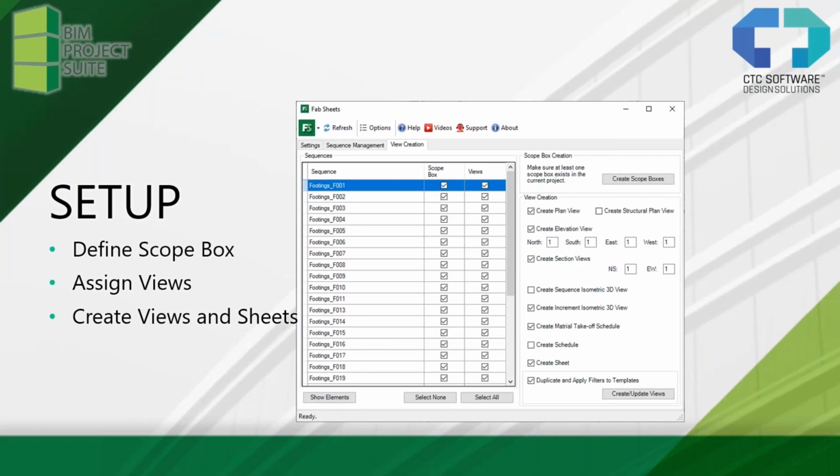And then finally, after we've got the increments defined and we've got, say, footings F001 through whatever, we need to get a scope box for them to help us define the viewport or the view extents, and then we can create all of these views. So plan views, or structural plan views if you want to go that route, the various elevations, sections, 3D views, a material takeoff schedule specifically, or just a standard schedule, and then the sheets. And the tool will create all that for you.